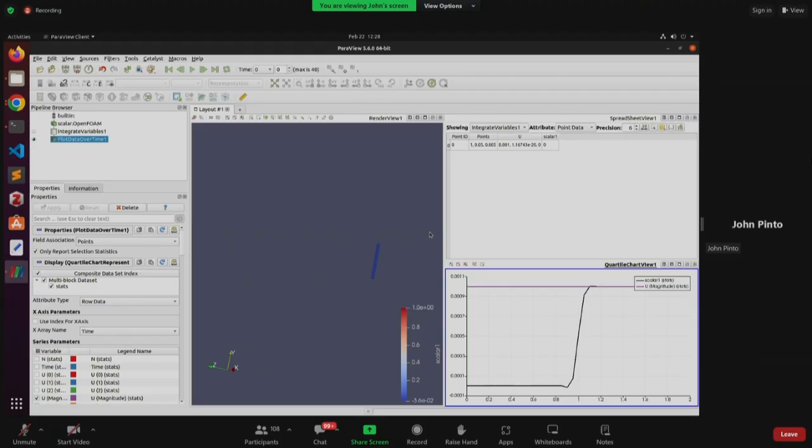Say you can inject tracer in a room where you've given an inlet to the room, where Professor Janni was talking about the room simulation, right? You can inject tracer at the inlet of the room. Then you can see when that tracer reaches one corner of the room. With that, you will understand at what time the fresh air is coming over there, or how much time the air has stayed in the room before it reaches there. So all these analyses you can do.